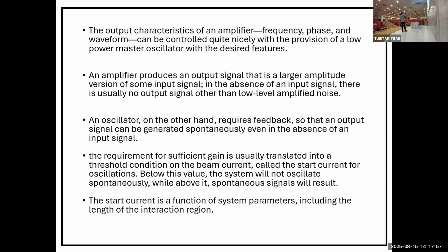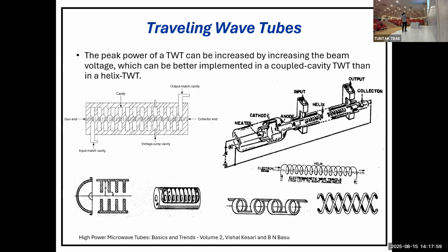And now let me move on. So the helix traveling wave tube, this is the first traveling wave tube for lower power, is a very great amplifier with a wide bandwidth. But you can't push it for high power because this small helix will have a lot of RF voltage and RF fields around it, and they can cause RF breakdown, and you could damage them.